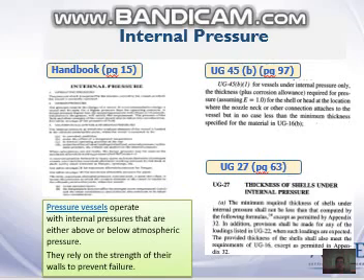Pressure vessels operate with internal pressures that are either above or below atmospheric pressure. They rely on the strength of their walls and flanges to prevent failure. UG 27, thickness of shells under internal pressure. This paragraph provides formulas to determine minimum required thickness of shells under internal pressure.